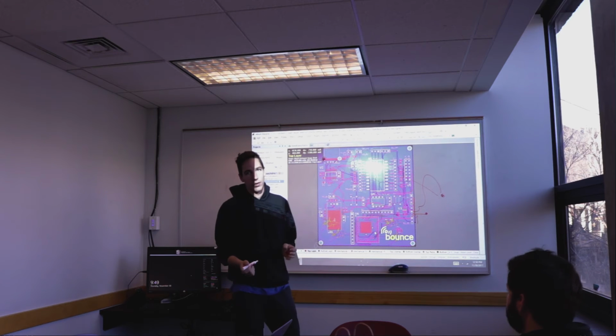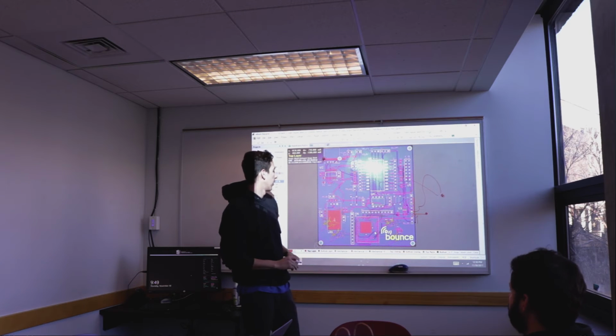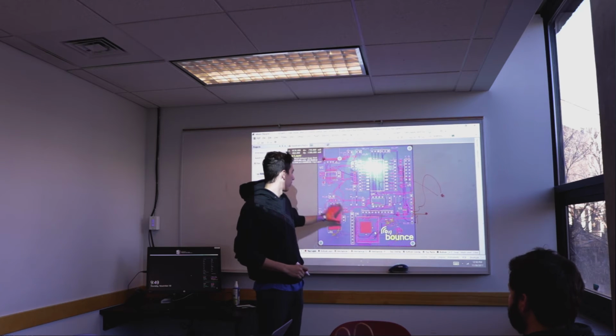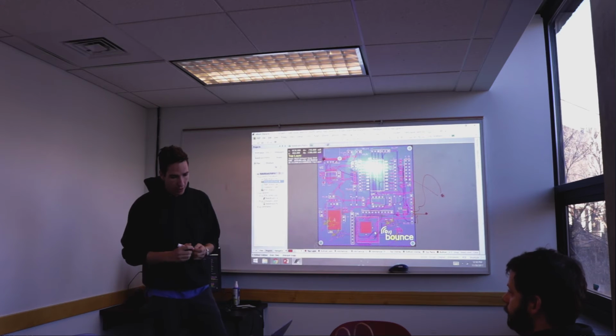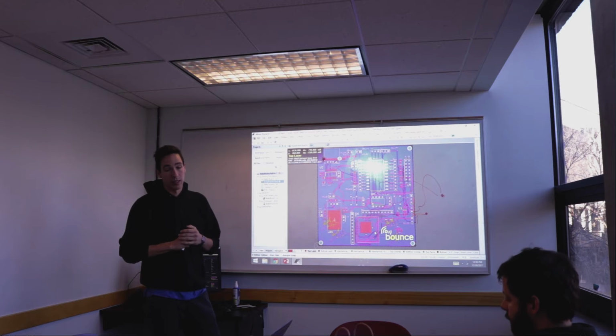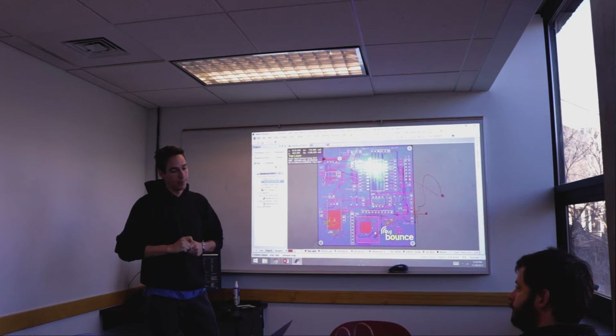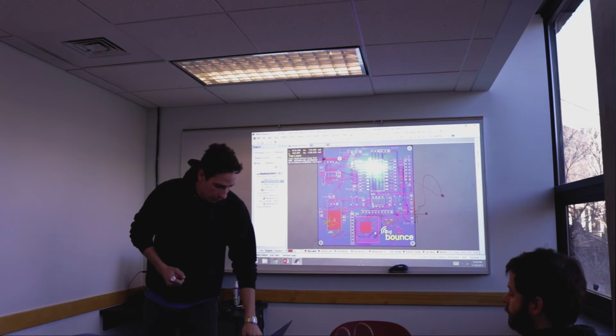So when you're designing things, it all starts with a layout, and you're going to want to group things together. By grouping things together, you can reduce the length of the return signal. For high-speed applications, you really want to group things as tight as possible. So that's a little bit of what I want to talk about.